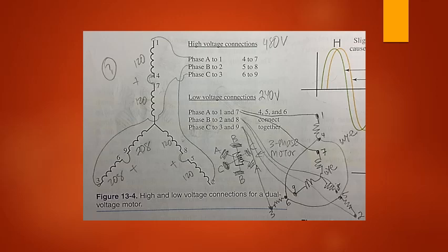First, the three-phase synchronous motor. The three-phase synchronous motor derives its name from the fact that it rotates at the same speed as the rotating magnetic field. This action is accomplished by using a squirrel cage rotor and embedding a set of windings inside of the rotor. The rotor windings are constructed much like an electromagnet. The motor starts the same as any induction motor and reaches near synchronous speed.